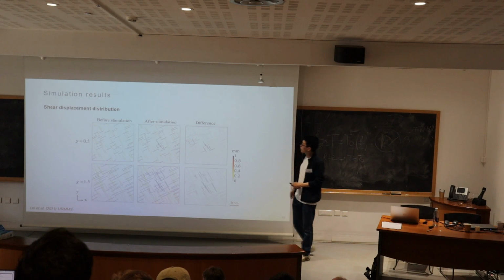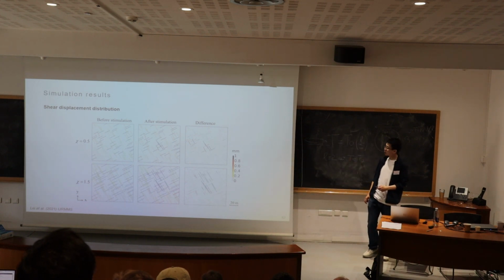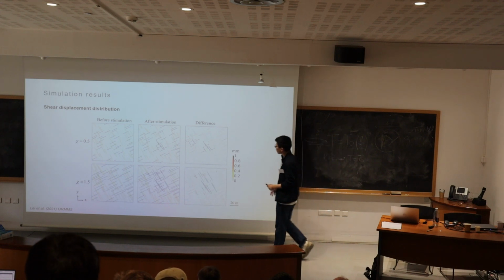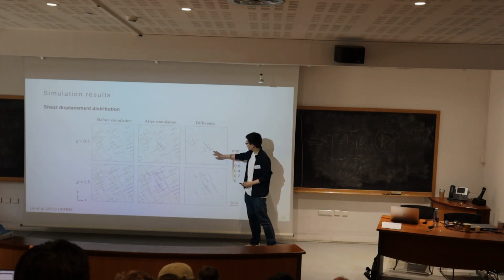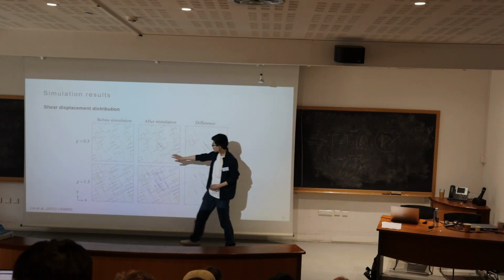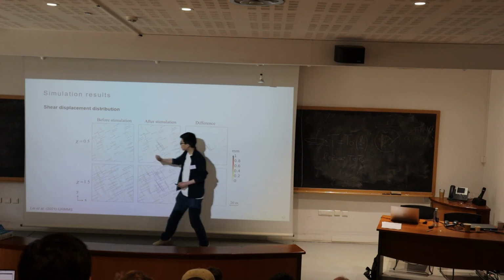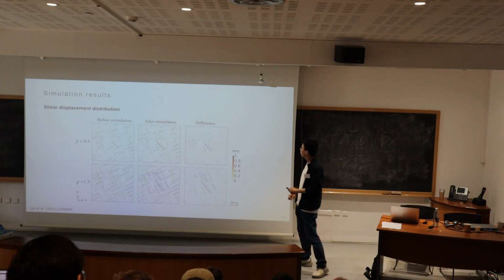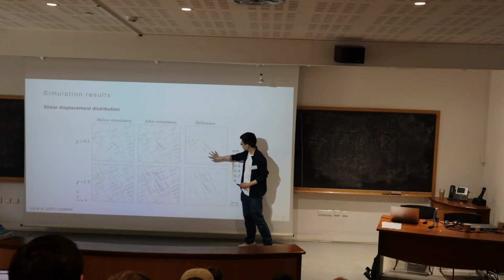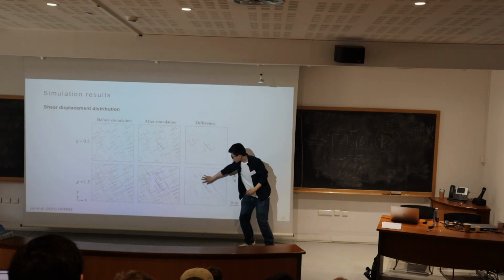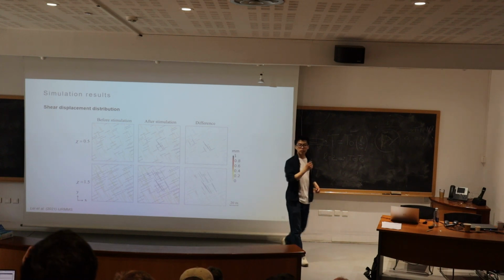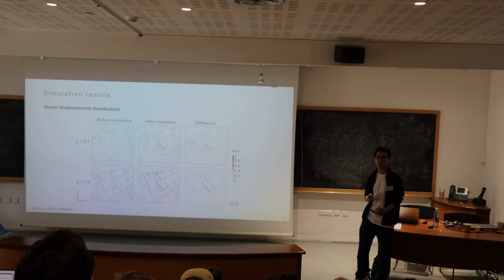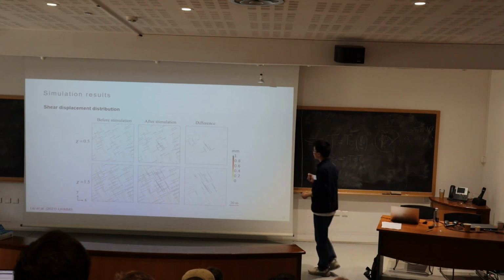Here I also further analyzed the shear displacement behavior of the fractured rock. And you can see for this fracture set, they are preferentially oriented originally to have large shear displacement. But after the stimulation, the more reactivated fractures are the fractures which are less activated at the beginning at the in situ stress.